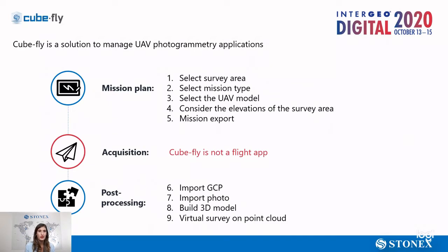Of course, this mission that you planned can be exported, and after you exported it, you will load it on your own app. You go in the field, you survey flying with the drone and collecting some ground control points. When you go back in the office, you do the post-processing.